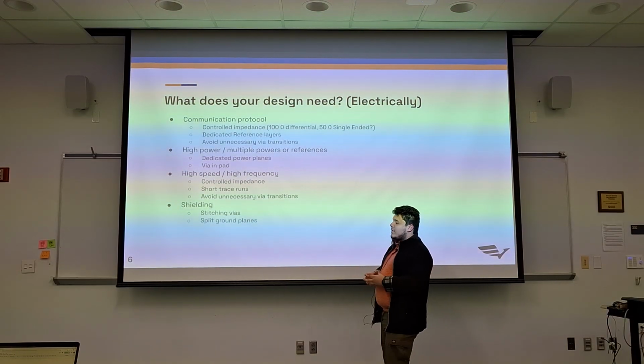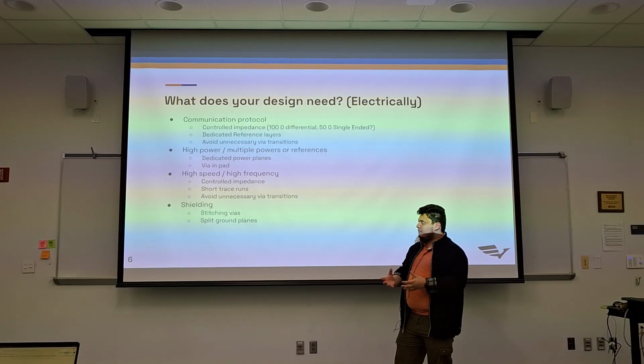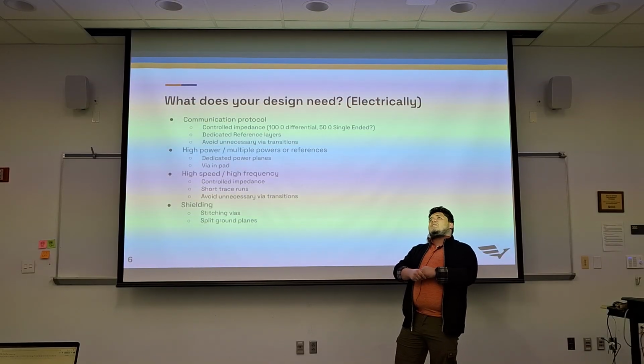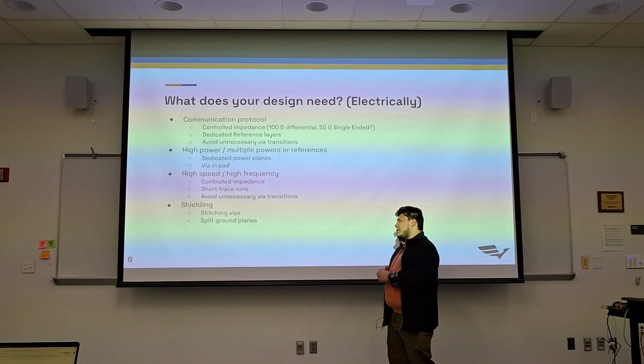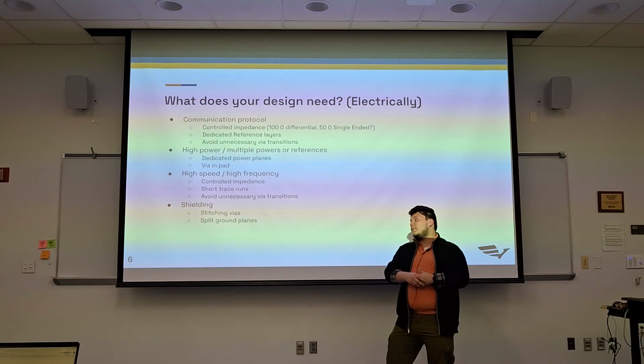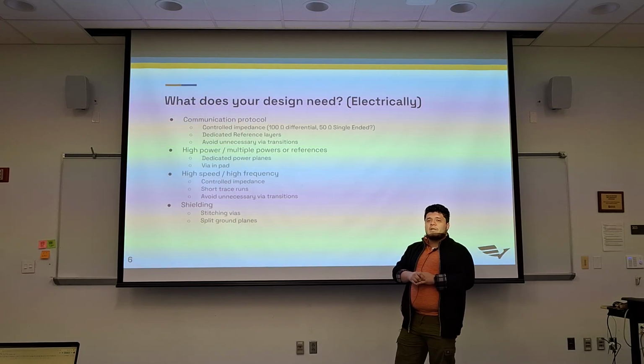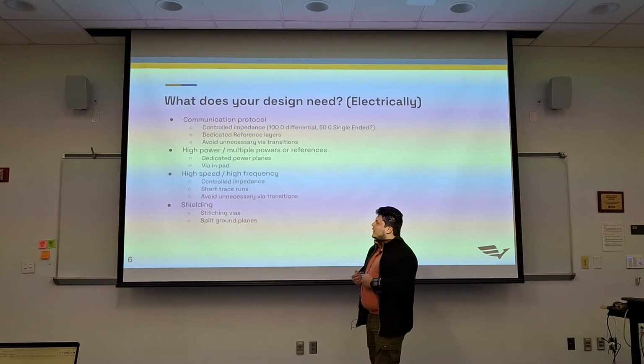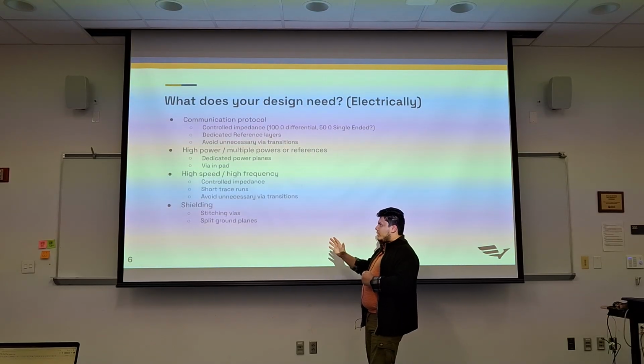You want to protect your boards not just from EMI, but for EMC, electromagnetic compatibility between the boards. A lot of the time you have to have really solid grounding in general, which is why we think about shielding.